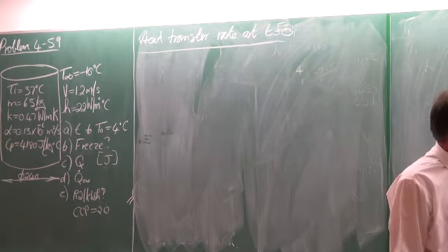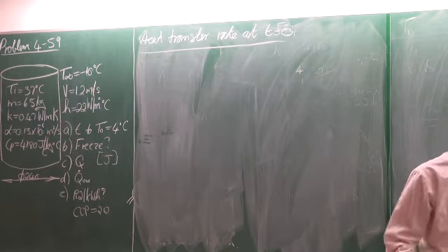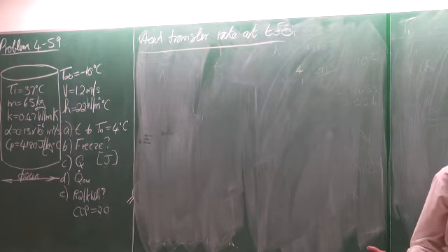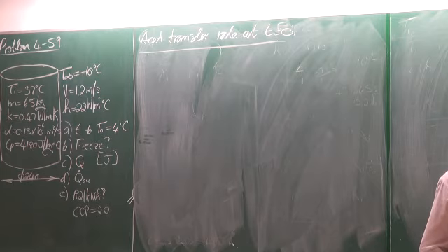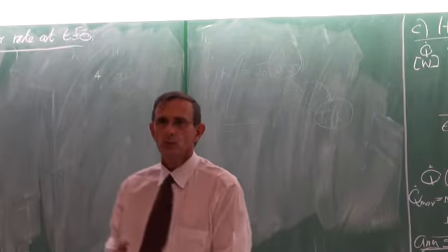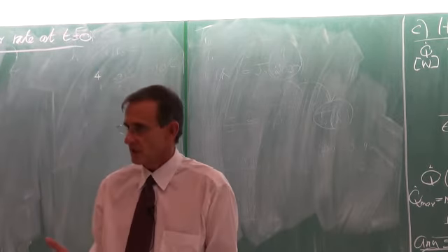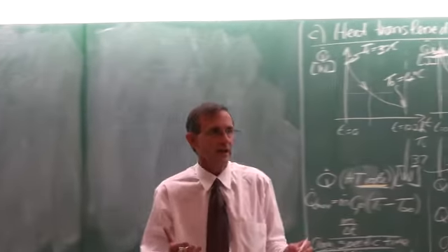The heat transfer rate would be this equation. Do you agree? Okay. But delta T is 0. So do you see what happens with this equation of yours? Okay. Obviously, you can say, well, that gives me problems, but I'm not really interested in what happens in the first milliseconds. I'll be happy with the first minute or so, and then you can do the calculation like that.